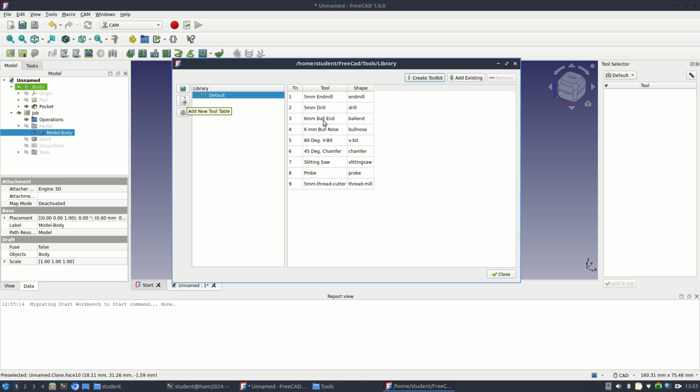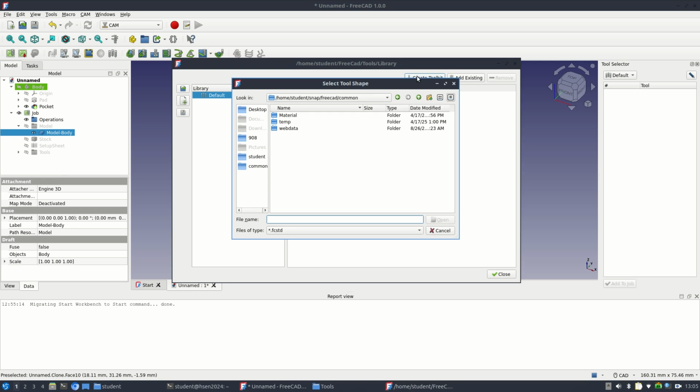and then you choose where your library with the default tool table is, right? So what we're gonna do is create bit. So we need to first select the shape. Shape does the basic properties of the tools based on what shape, if it's rounded, if it's square, if it has cutting edges. So we had to go back and find our shapes.